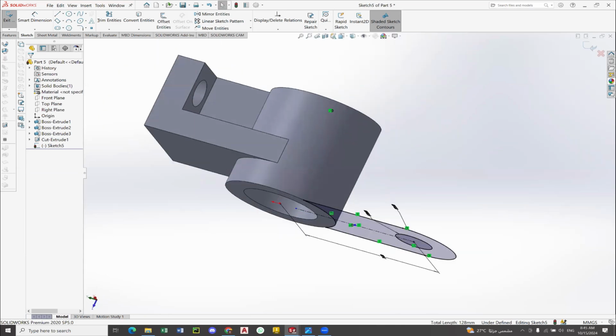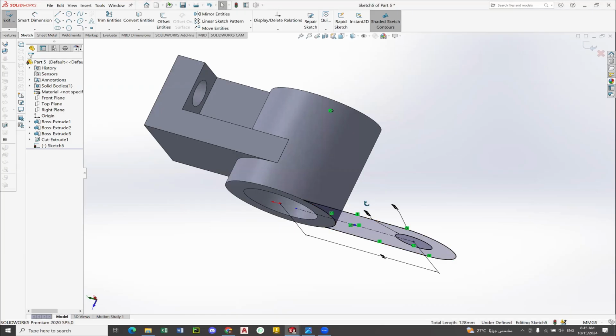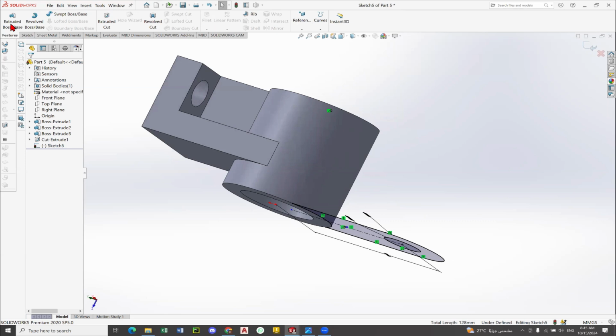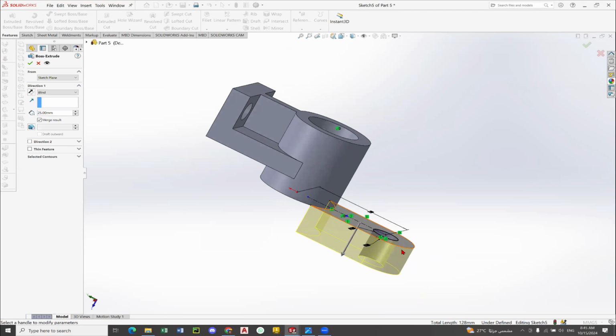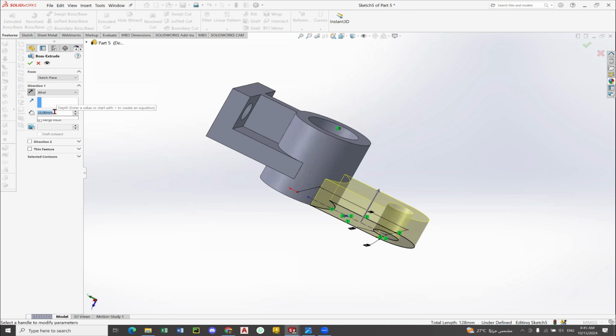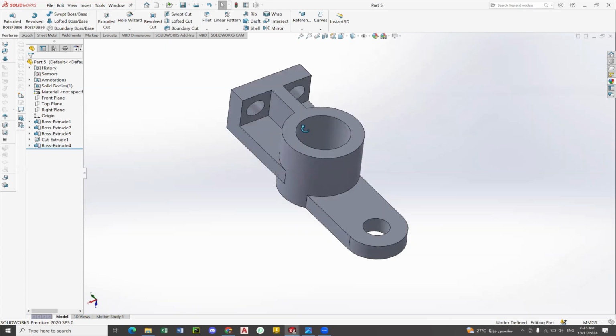and do an extrude of 15 millimeter as mentioned here, right? 15 millimeter. Feature, extrude. Like you see here, I should change the direction by clicking there and putting the height here, typing on my keyboard 15 millimeter, enter. Okay, and save and rotate it. Perfect.